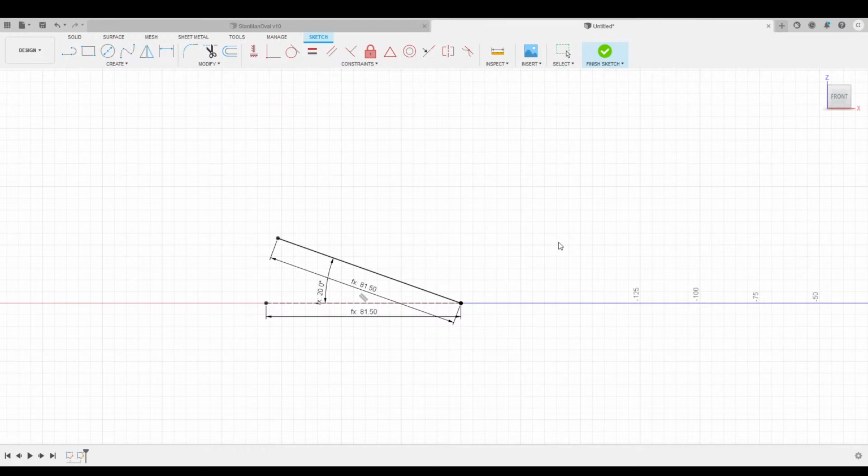2.25. And so what this is actually doing is we're setting up to match Hot Wheels track almost exactly, so that when we put in our little angles down at the bottom of this track, it'll sync up real nice, and you won't get any clipping with your cars on the sides. And then we got track wall. Since we're doing that, track mid wall thickness. In this case, we use 3 millimeters for the inside one, for the middle one.